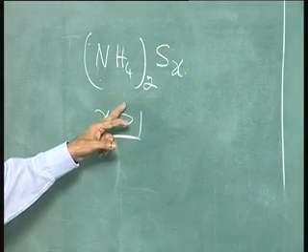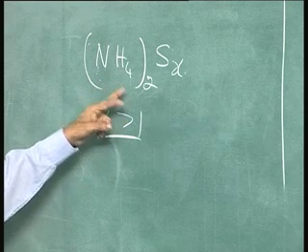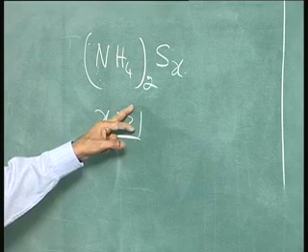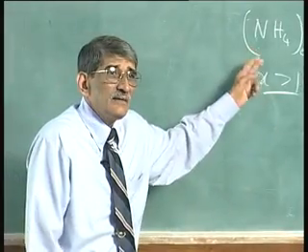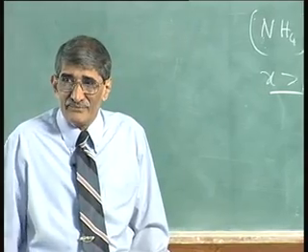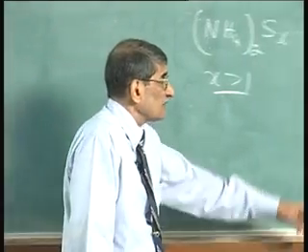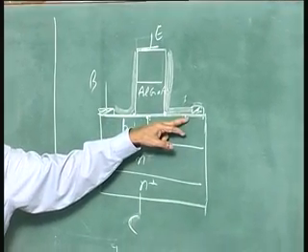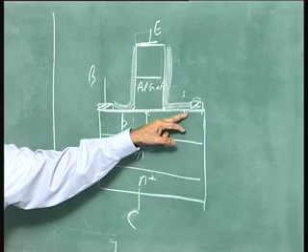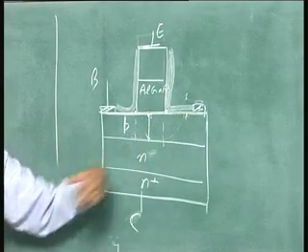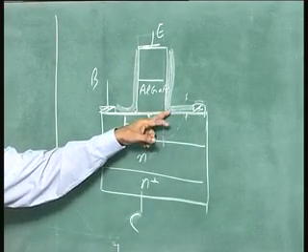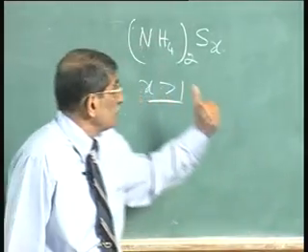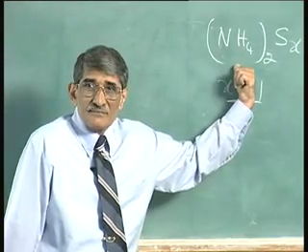With this solution, what happens is this solution reacts with the oxide layer. It removes the native oxide when it is in the chemical, plus it also removes a thin layer of gallium arsenide. So, when you do the treatment, you have got the surface cleaned of the oxide layer and the surface also has a layer etched out. Any junk, to use that language, any bad layer that is present on the surface, that also is removed. You have got a fresh surface exposed, with which ammonium sulphide will react and passivate it nicely.